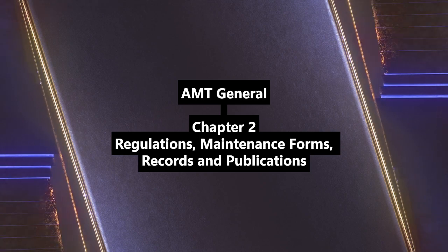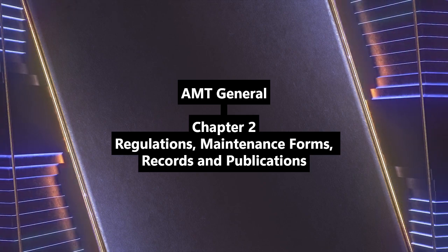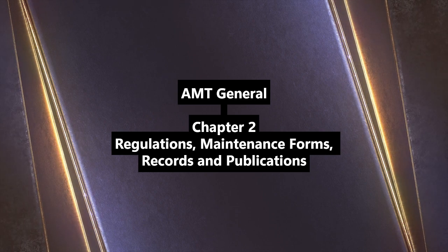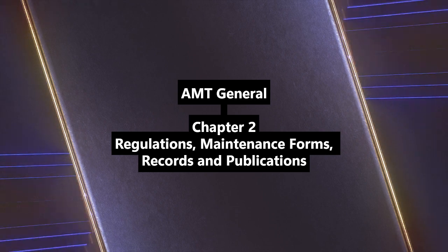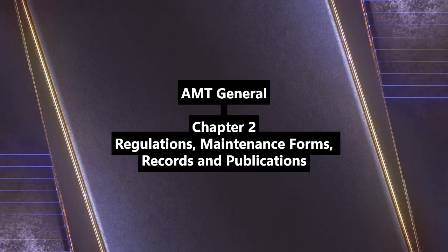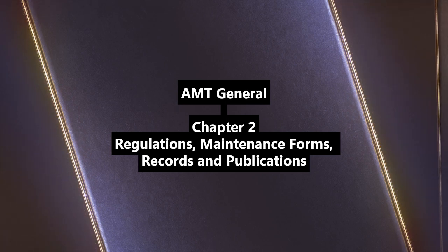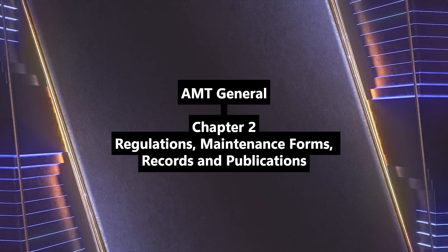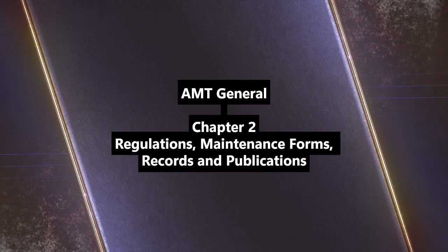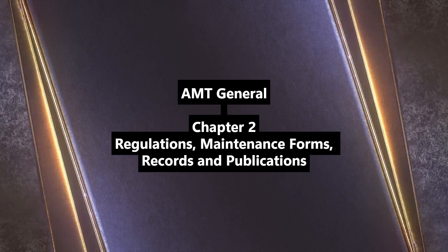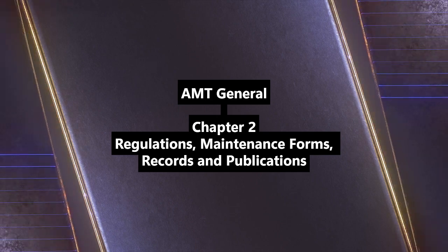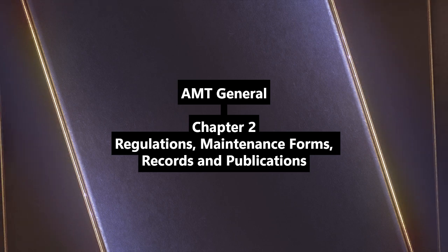Okay. Now things get more complex for air carriers and commercial operators. They do. To understand those rules, we first need a quick look at 14 CFR Part 119, certification: air carriers and commercial operators. This sets the stage for Parts 121, 125, and 135. Exactly. It determines which of those operating rules apply based on a few criteria. Like? Is it private carriage or common carriage? Is it for hire or not for hire? Is it a large or small aircraft using that 12,500-pound cutoff?